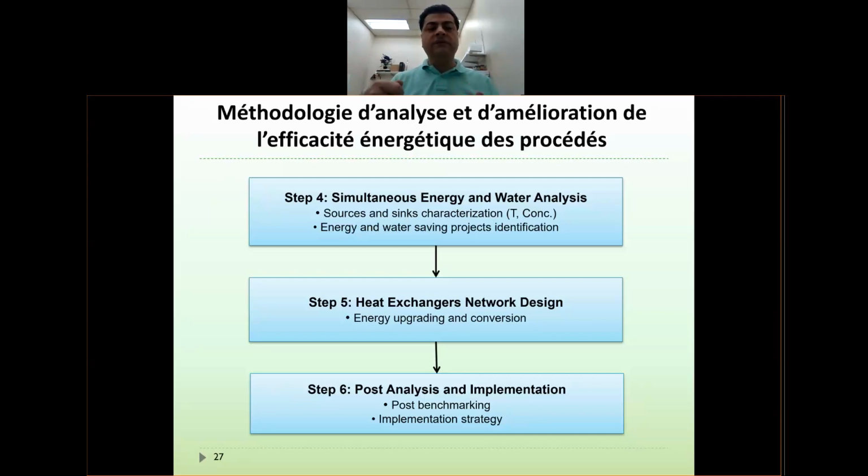So you always identify that, for example, the number of process-to-process heat exchangers that I have designed at a certain point are not perfect. So maybe you need to consider bypass or supplementary or backup heat exchangers. These are things that make your process robust, or you can prevent inefficiency in the process.